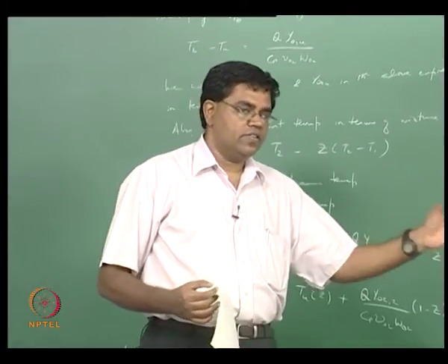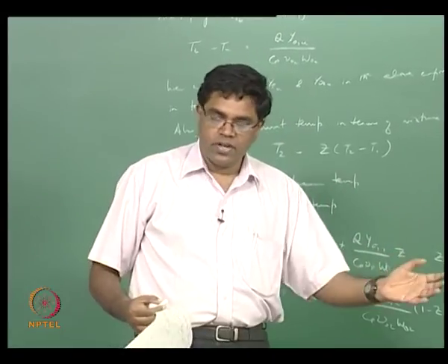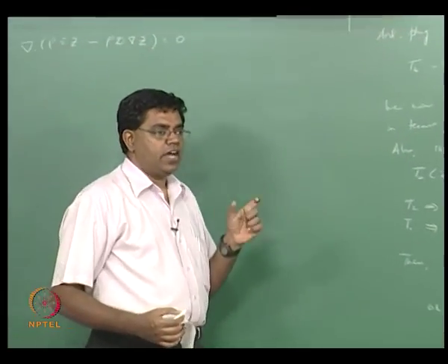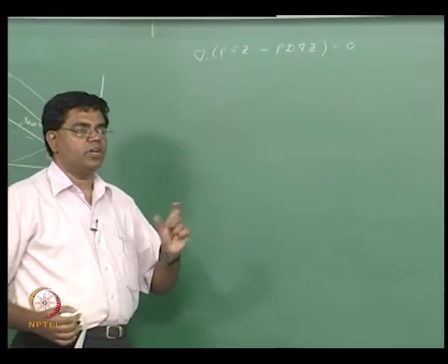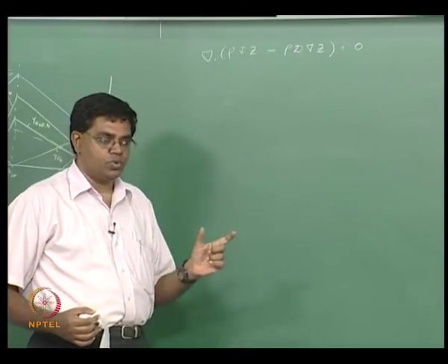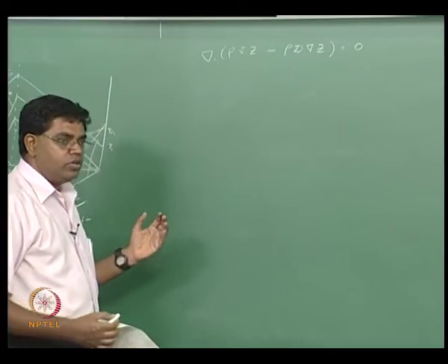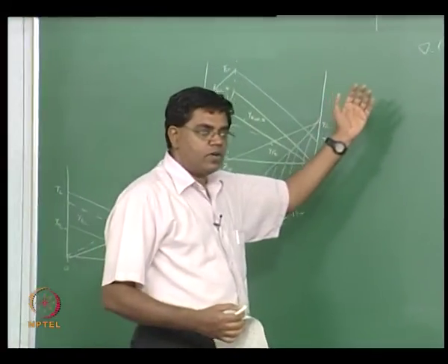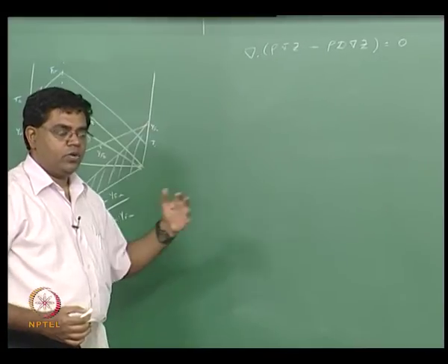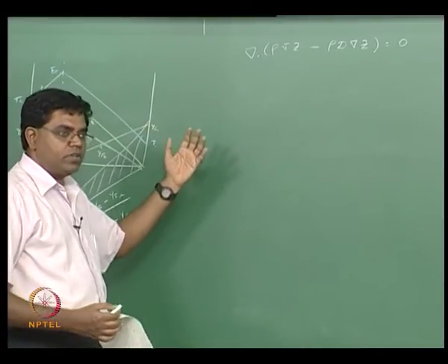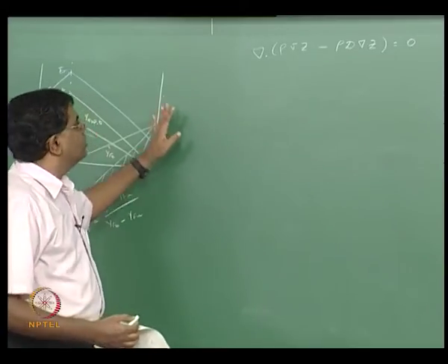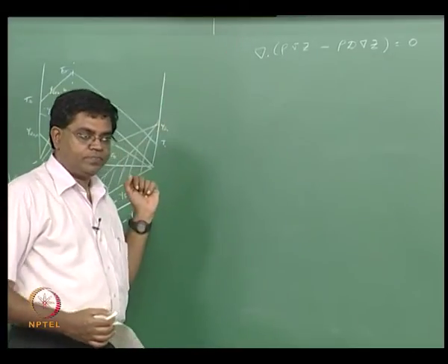All the things that are getting added up and divided by are constants which depend on the inlet concentrations, but what's really happening is you're now forming this coupling function, nu YF minus YO2. If you now use the evolution equations for species concentration YF and YO2, multiply by nu, subtract one from the other, add something else, divide by some other constant, and so on, you should now be able to get this.